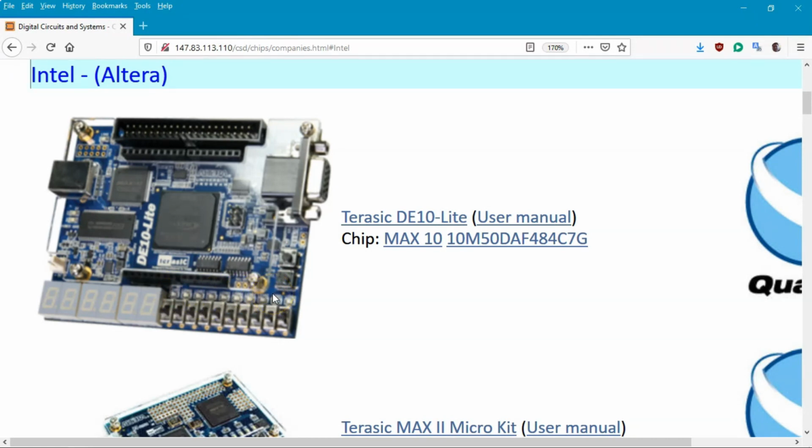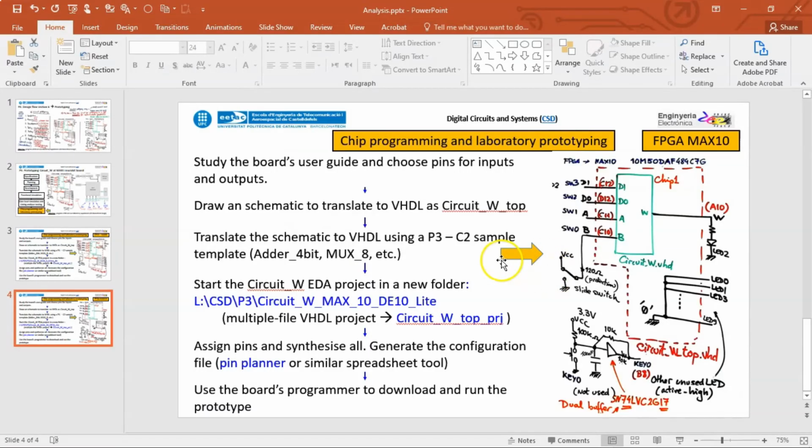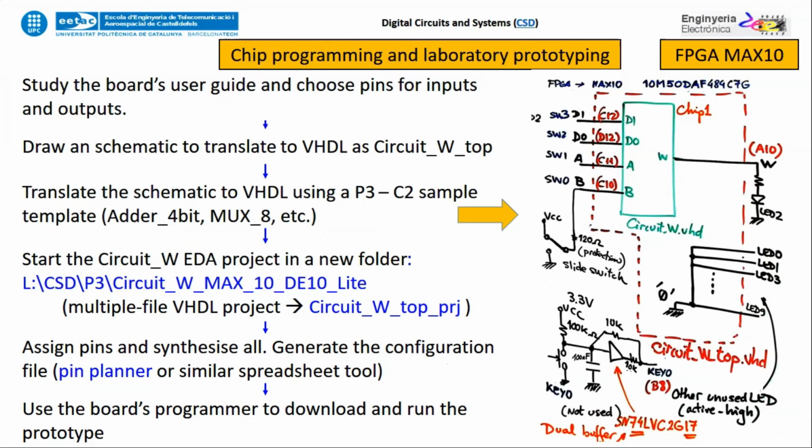So it's going to be good practice, the same as before, to switch off all the LEDs which are not of interest. But you have to check the user manual to see whether these LEDs and these switches are active high or active low, or common cathode or common anode. So by inspecting the user manual, you will know the right level to drive the inputs, to take information from the inputs and to drive the outputs. You can do that very well here, and there is nothing else to say. It's simply a repetition of the same experiment.